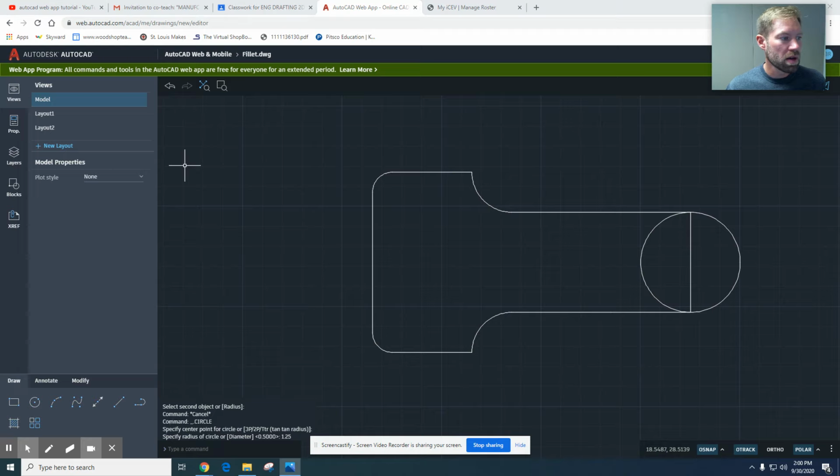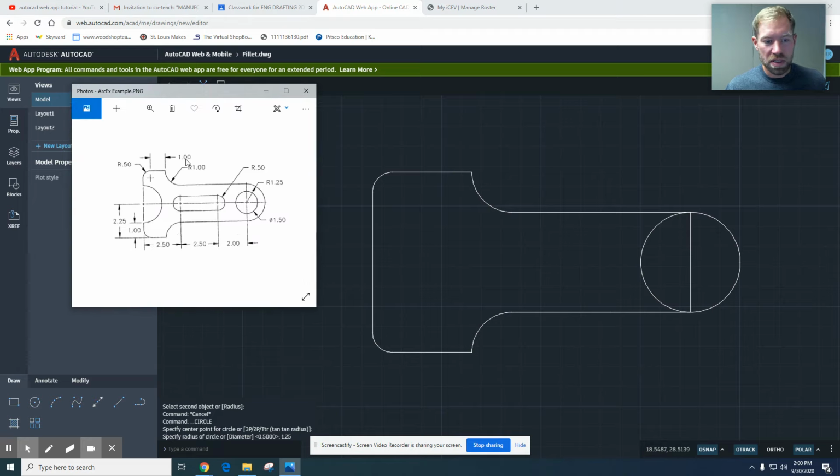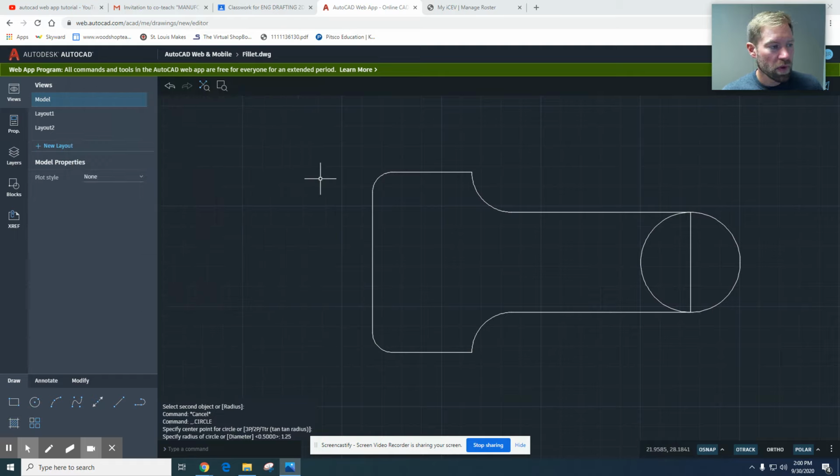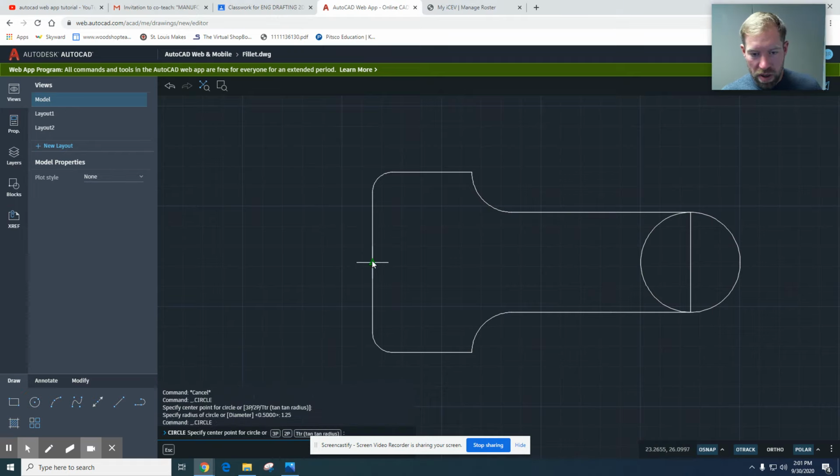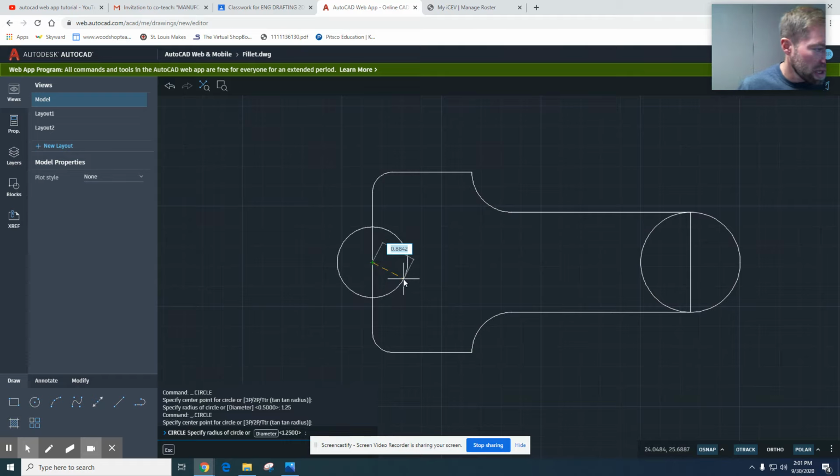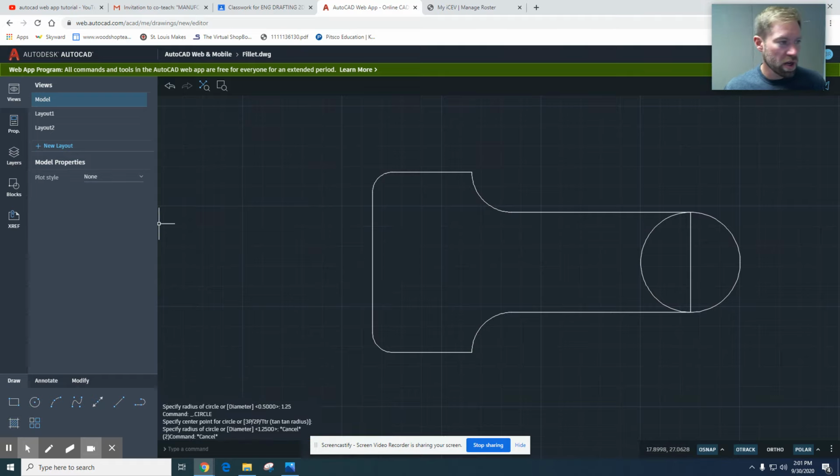I'm going to move our image back in for a second. So we have this outside radius placed tentatively. I want to do this big circle now here. So we have to determine where is that located. So from the bottom of this to the middle is where that circle wants to go. So we're going to snap to midpoint again. I'm going to move that out of the way. I'll draw another circle. It's going to come right here to the midpoint, and that circle diameter, now we have to do some math. I'll show you guys why.